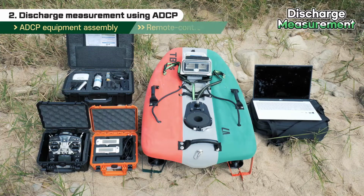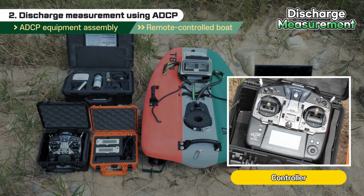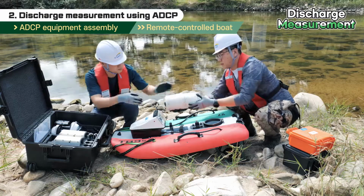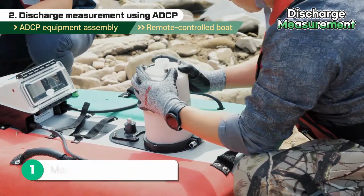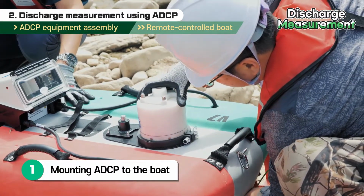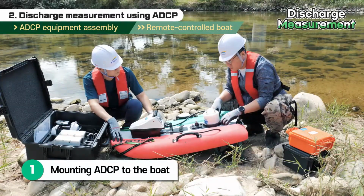The discharge measurement equipment using a remote-controlled boat is composed of a boat, sensor and communication box, controller, GPS, and laptop. We assemble the ADCP equipment ourselves. ADCP is mounted on the front part of the boat using pins so as to ensure it does not move. Since the sensor protrudes under the boat, the on-site worker should be careful not to scratch or bump it.